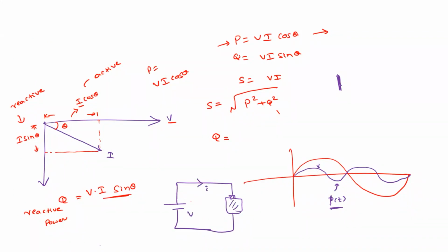So this is VI, right? So this battery will take the energy, or it will deliver the energy. If this is, for example, 10 amperes and this is 50 volts, what is the power absorbed by the battery? 500 watts, right? So that means the power is positive.